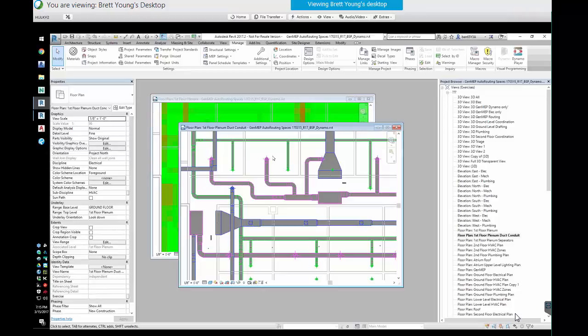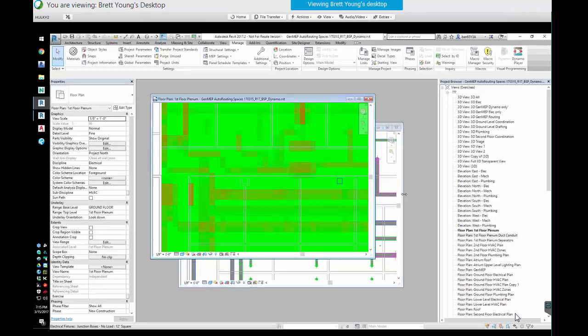The way we really think about it is maybe a user would create a Revit space from the drop ceiling to the floor slab above in the whole plenum area, and those heights can vary, right? I just want to chop that into a 1 foot by 1 foot grid. I don't care what the height is, and the math will change, right? The volume divided by the total volume of that column will be variable because the column is changing. In this example, they're the same. But yes, you would create a Revit space and then chop that up into 1 foot, or even more resolution if you want it.